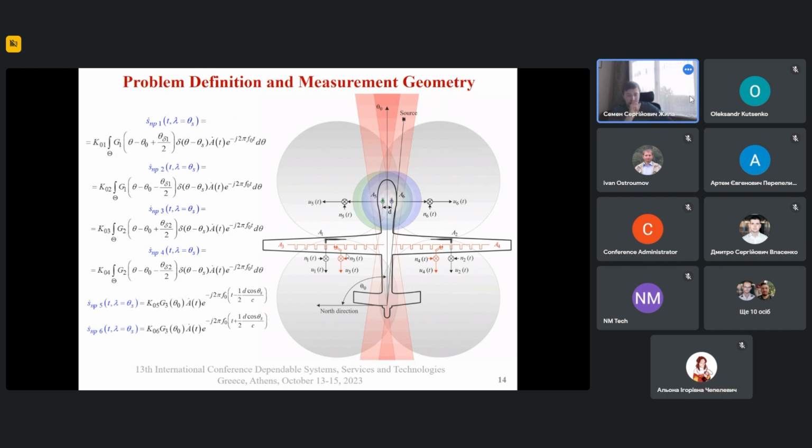We propose to use a Franklin antenna. It is a directional antenna with relatively narrow beams, and the length of the wings allows us to put this antenna. And in front of our UAV, we propose to insert two omnidirectional antennas for the phase detector. And in this case, we have five signals, like 4 of them you have already seen. And for the fifth one, in the omnidirectional antenna we do not take into account the characteristic of the antenna patterns. We just get the antenna gain,